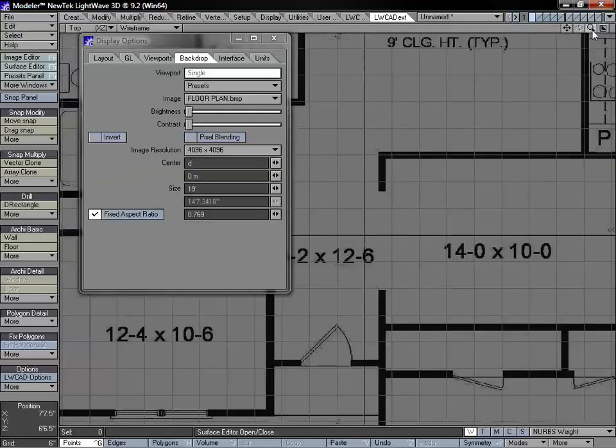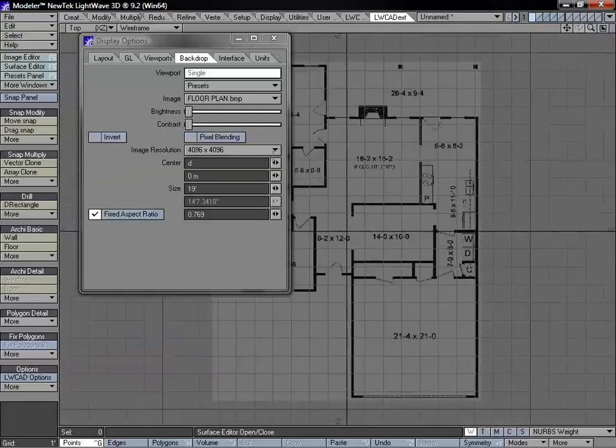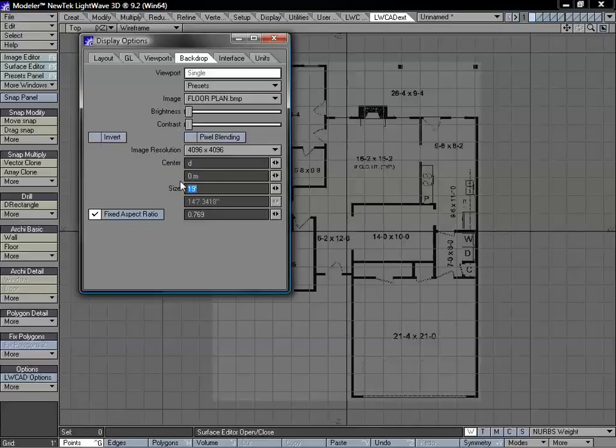Another thing we need to make sure we do is include the foot number or the foot sign afterwards, because if we just push enter with a regular value, currently right now it's going to still stay in sort of metric and then convert it. So just remember to put the foot sign and the inches sign if needed.